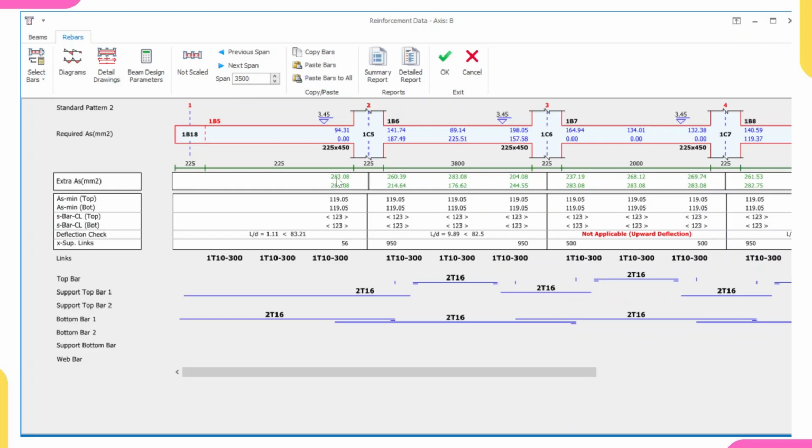But if you are in a country like Nigeria or other African countries, make sure it's not less than 100, because in Nigeria, Y16 is no longer Y16. Y16 might just be Y14 or even Y13. And the yield strength that you are telling us is 460 might no longer be 460; it might be 420, 430, or even 410.